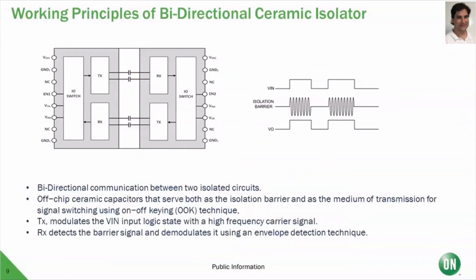Looking at the working principles of the ceramic digital isolator, the electrical and the modulation scheme is similar to the on-chip isolators, where we use on-off keying. What that means is when you have an input signal that is low, the modulation is not passed through the capacitors and the output stays low.